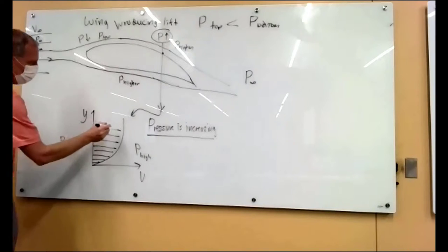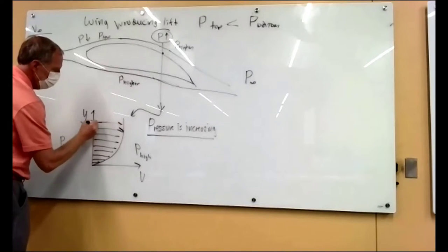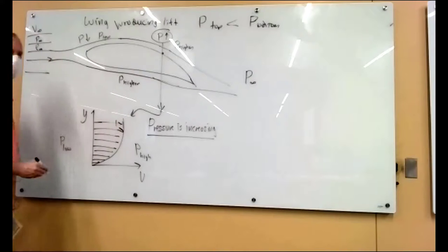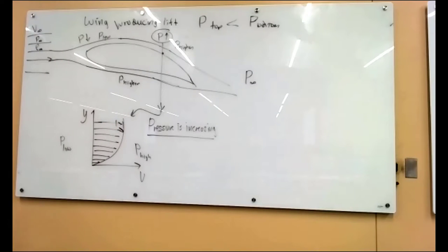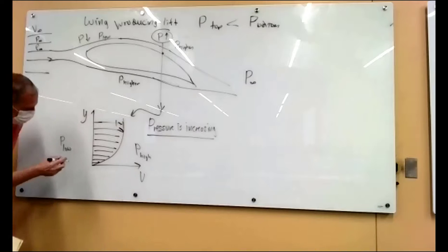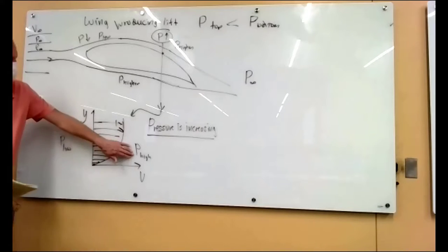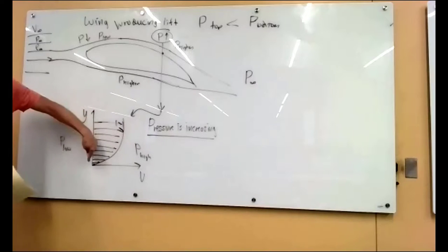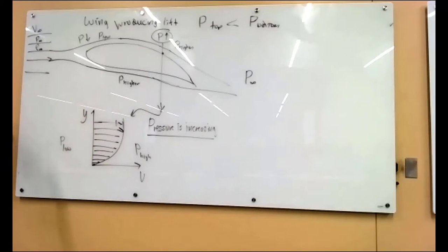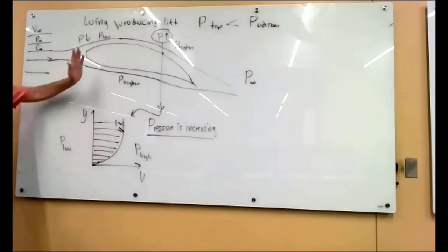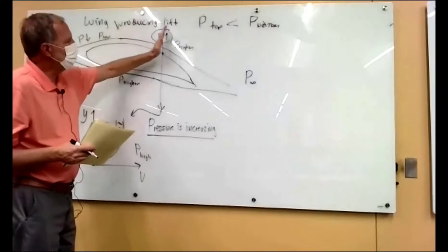Well, with these high velocities up here, the flow gets slowed down that much, and it's still going forward. But when you get down here really near the surface where the velocity is really low, that pressure force will slow that flow down so much that it'll actually start going backward. Because remember, we're moving along here, and so we're going region, region, region, region.